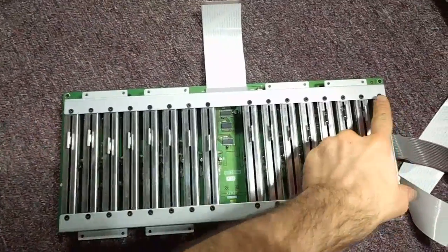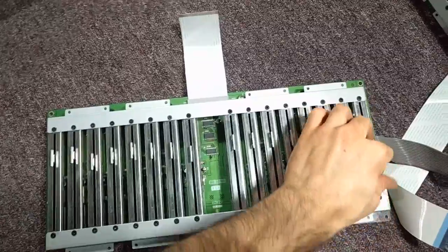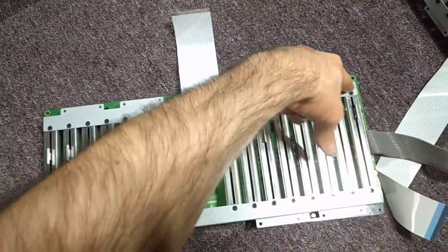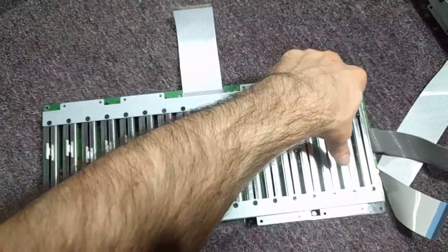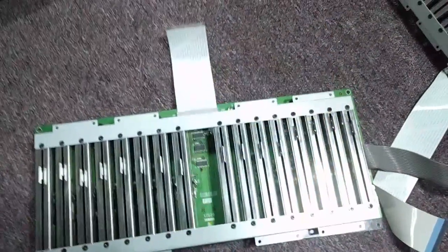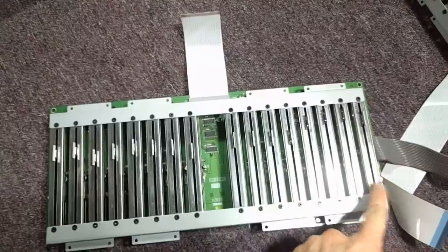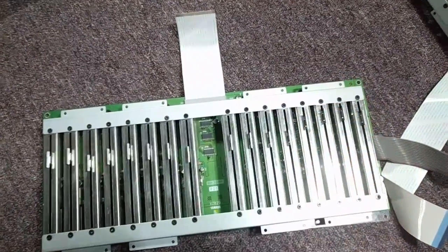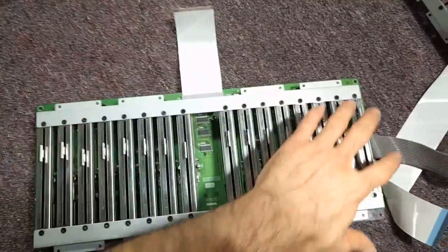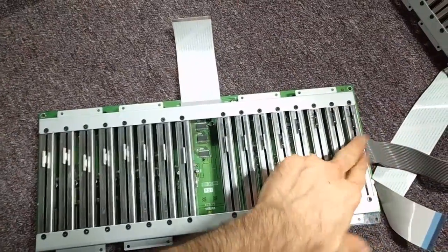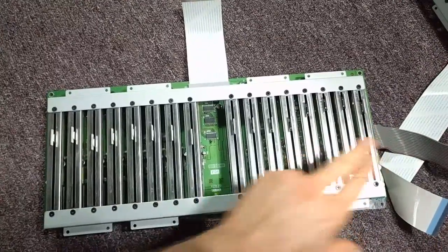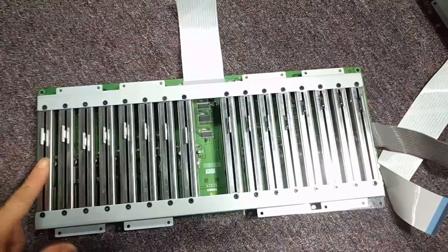And this one had kind of a stiff belt in the slider, and it turned out that was from gunk in the pulley that's over here on the top. There's a motor with a little gear bit, and there's a pulley on the other side. The pulley was kind of gunked up. So I took that apart, and also used this as a reference slider to repair this one. And this was the really bad one.